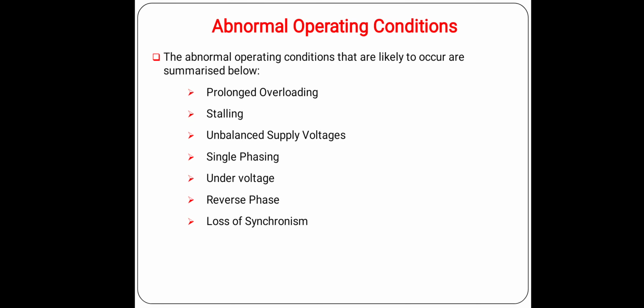Reverse phase. The name already explains what reverse phase is. Basically, the direction of rotation of a polyphase motor is reversed if the phase sequence is changed. In some motor applications, such a protection may become an essential feature of motor protection.